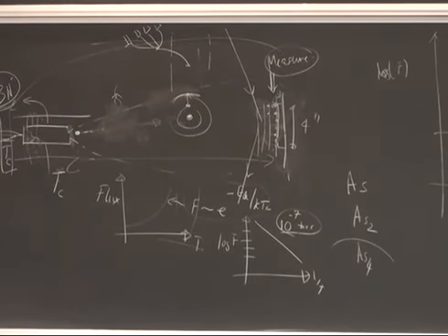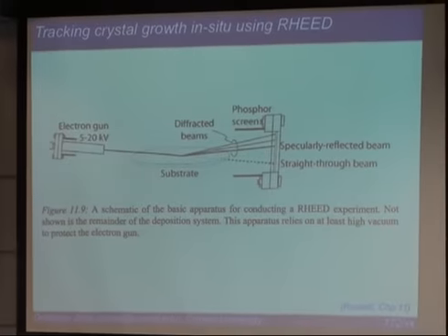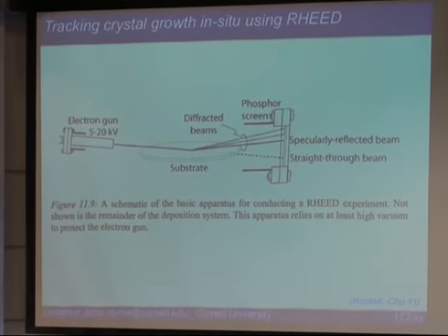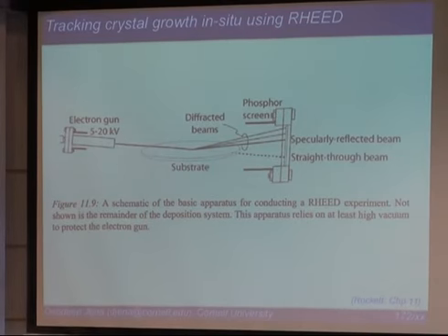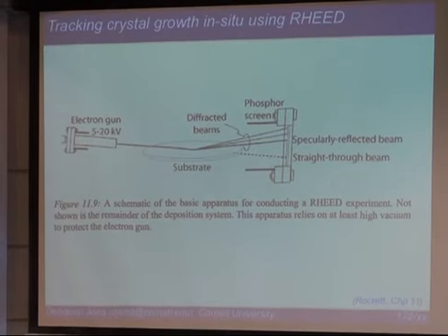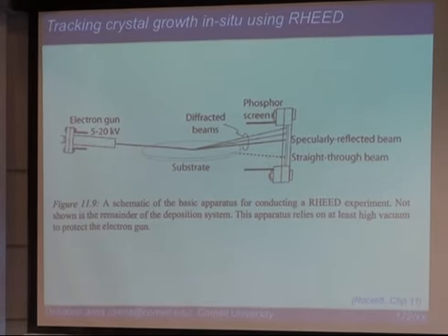So as you are growing that crystal layer by layer, you now bounce off electrons. Right? And electrons are relatively easy to create. So you have essentially a very low electron affinity metal. Typically these are metal wires coated with cesium. Cesium has a very low electron affinity. You apply the slightest voltage and electrons just want to leave, so they want to go into vacuum from the metal. They field ionize very easily. And so you create an electron beam.